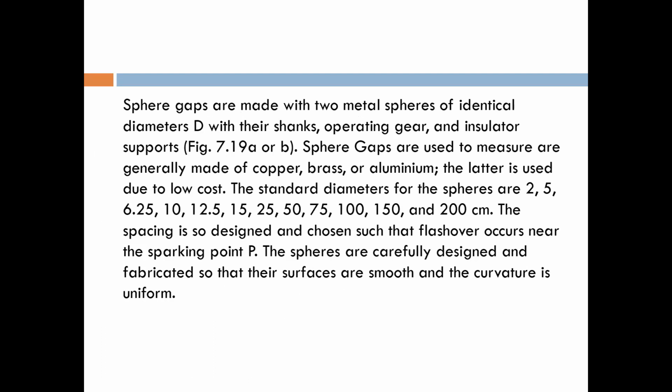The spheres are carefully designed and fabricated so their surfaces are smooth and the curvature is clean. The surface should be smooth. They should not have dust. They should not have grease. Remember that the sphere we are using should not have dust or grease. Otherwise, you can't get the accuracy for which the sphere gap meter is used.